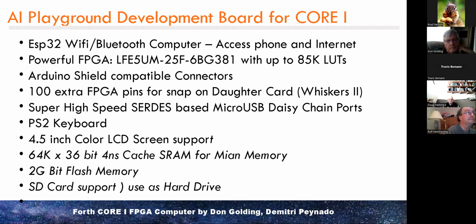So if you plan on gaining support for a lot of the old Arduino Uno shields, you'll need 5 volts. If you want compatibility with anything made more recently that isn't marketed specifically to Arduino, you probably want 3.3 volts or even optional 3.3 volt / 1.8 volt.